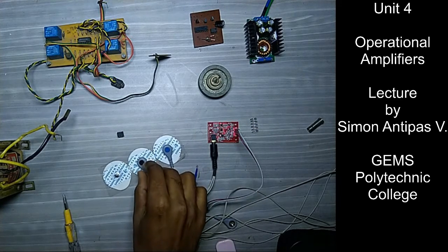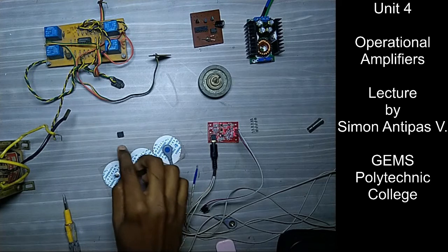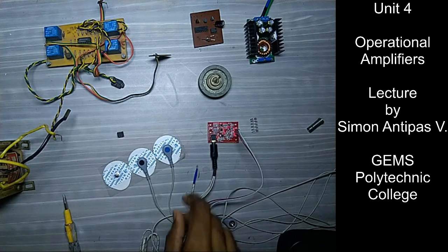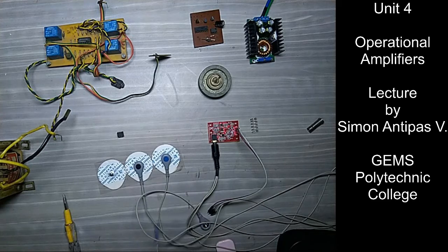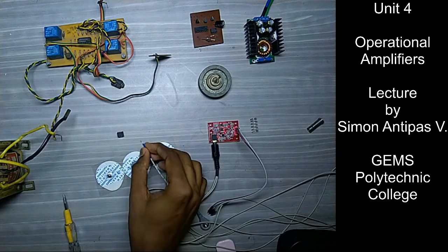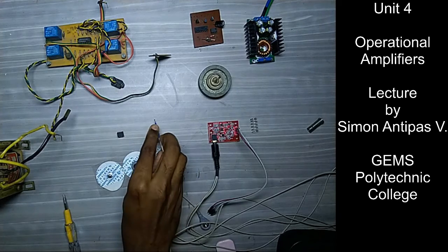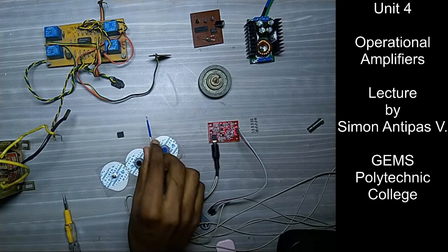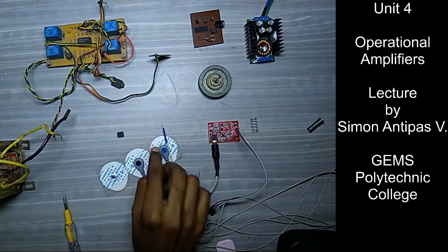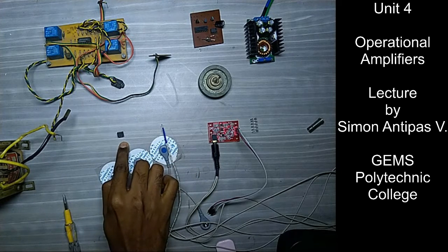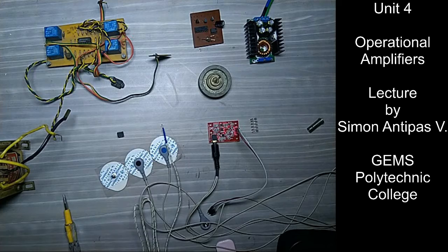Yes, and you also have requirements in temperature measurement, in this case, a thermocouple. There's a small voltage generated between these two different metals when I keep this temperature probe on a surface to measure its temperature. And such precise low voltages can be measured with an operation amplifier. Let's look at it in detail in this session.